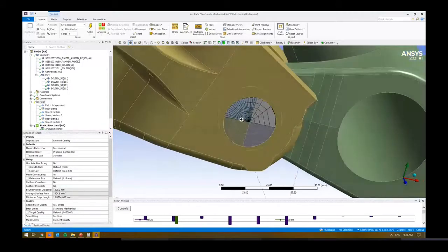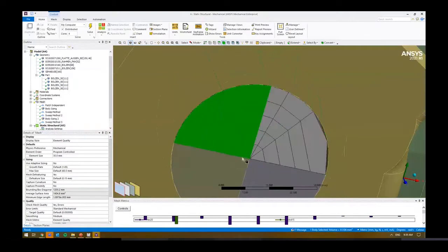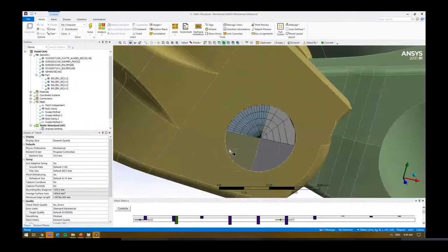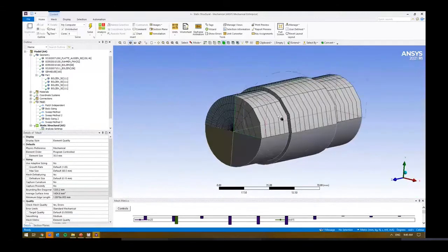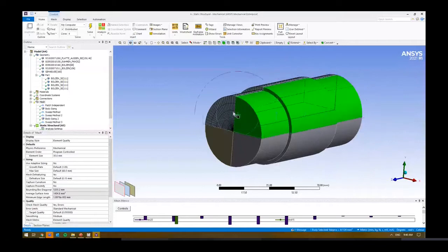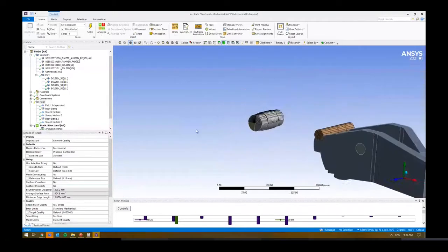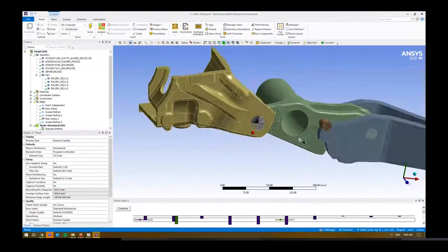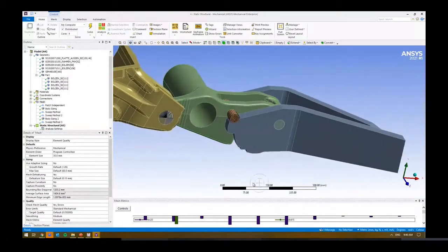Over here again, you can see I did it the first time, it didn't quite work. I added some sizings and then some sweep controls, and I've got a high quality grid. And then I can start to refine around some of these regions. Right, you'll see again, you do it again, you forget to add the sizings, and this is what it's giving you as well. So you need to play around with it. The first thing that you do may not necessarily work as well.